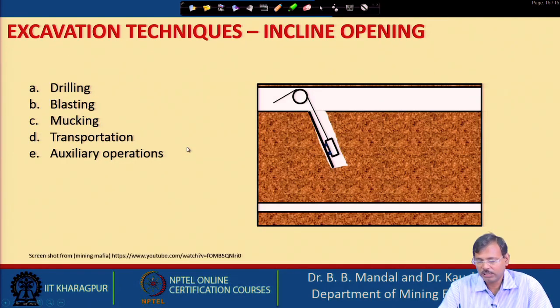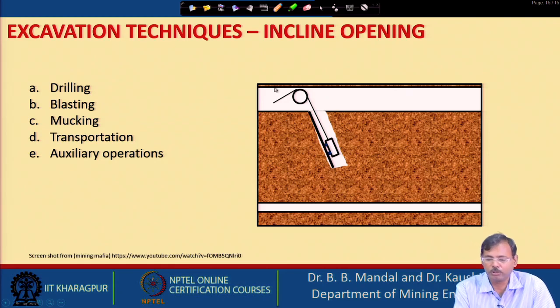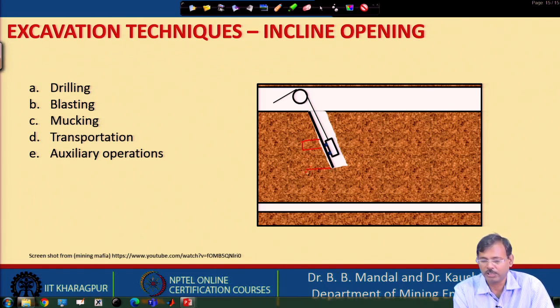So, this is in general the provision during the excavation. Along with that, the rails are provided, so that the skip is allowed to move on this rail, and whatever excavation is carried out, that can be taken into the skip and taken out. And from time to time, those platforms are provided at different levels as the storage place and machine shifting place that can be utilized.